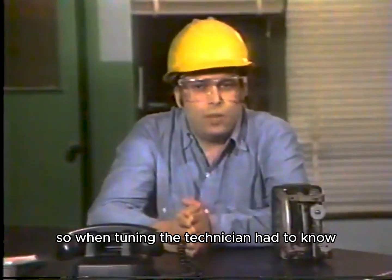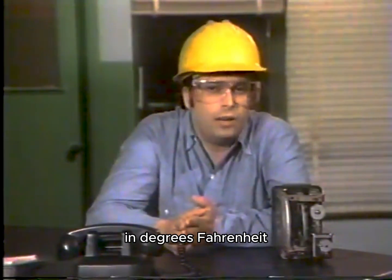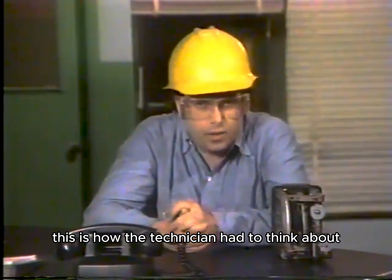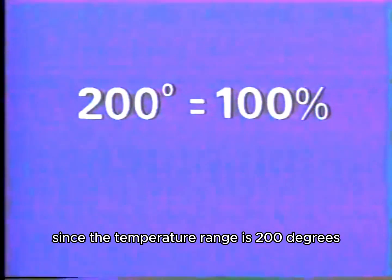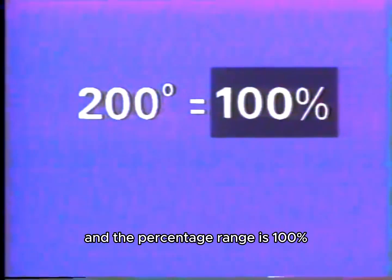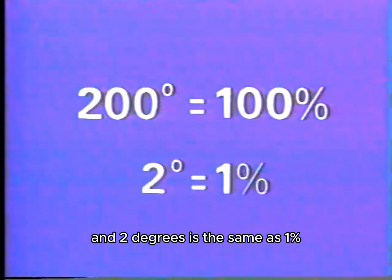So when tuning, the technician had to know the relationship between temperature in degrees Fahrenheit and percentage of temperature range. This is how the technician had to think about the indications. Since the temperature range is 200 degrees and the percentage range is 100%, then 200 degrees is the same as 100%. And 2 degrees is the same as 1%.